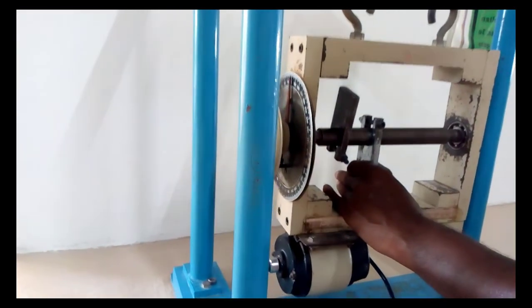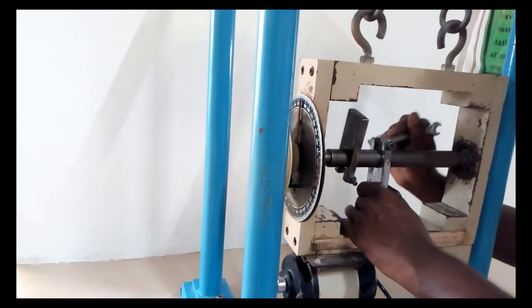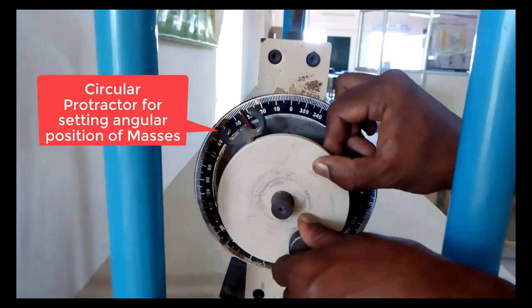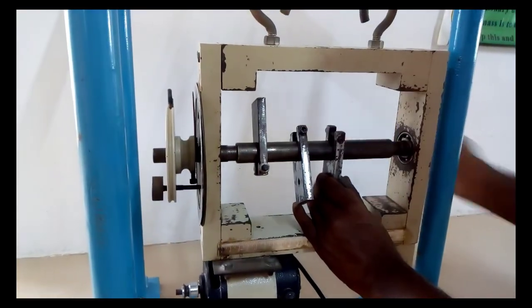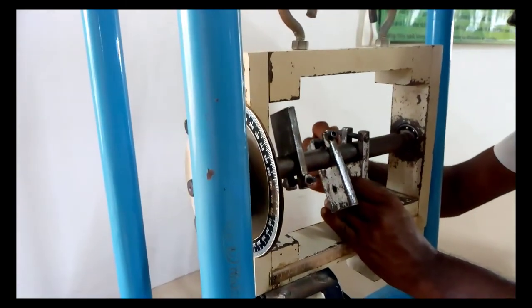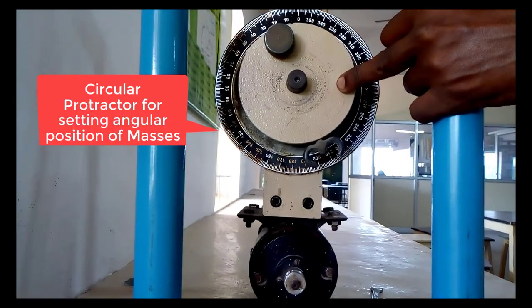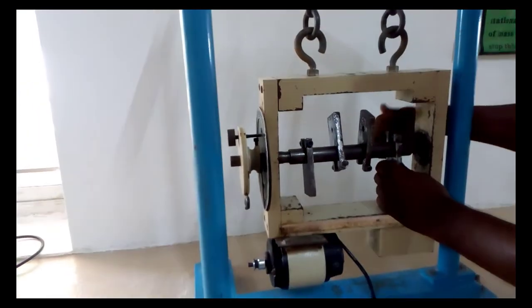As far as the distance is concerned, each plane is located 50 mm from one another, equidistant from one another. We are going to put this second mass at exactly 50 mm from this first mass. Also we have to make sure that the angles are exactly referred from the horizontal. Now you can see that these four masses are aligned based on the angular settings that we have calculated, and the distance is also exactly positioned based on the given case.